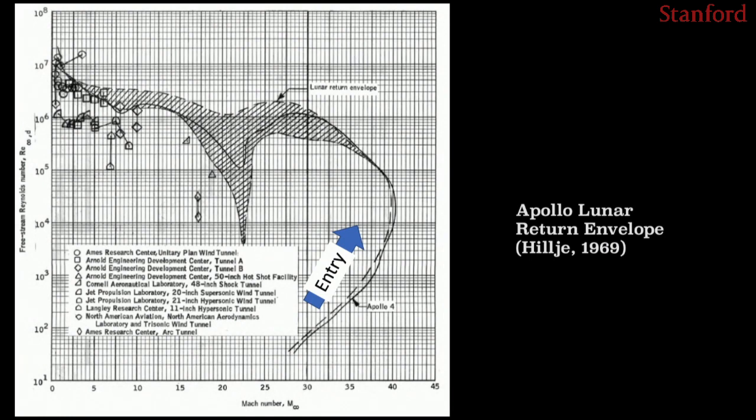The reason for having that elbow there, where you see that the Mach number first decreases, is actually small, and then it increases, and then decreases. That may perhaps be counterintuitive with what we have learned before, that the Mach number and the velocity actually decrease through the atmosphere.